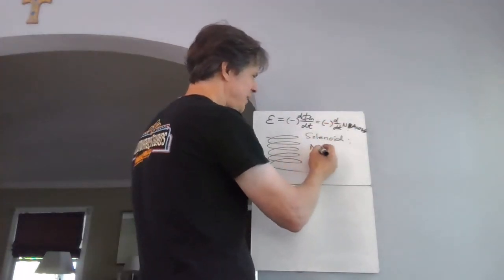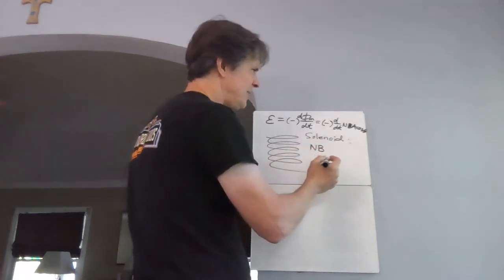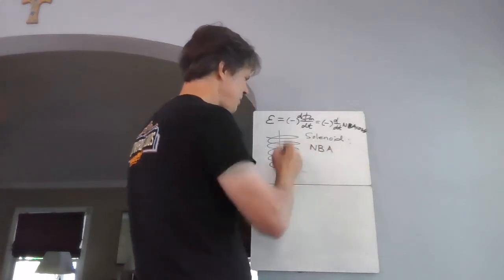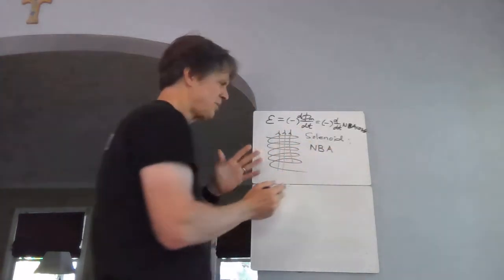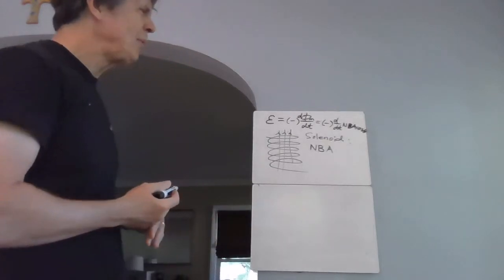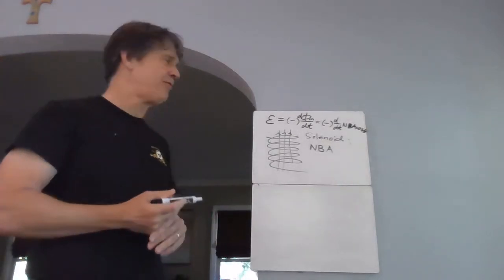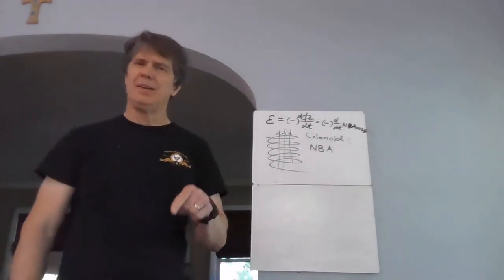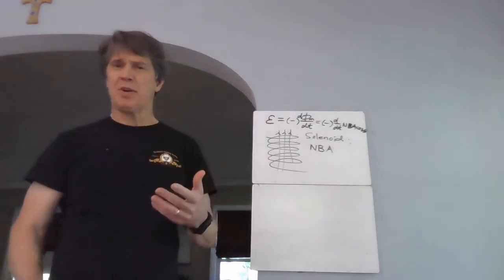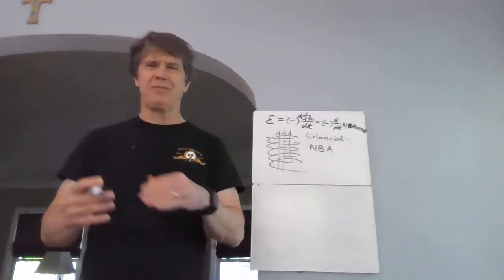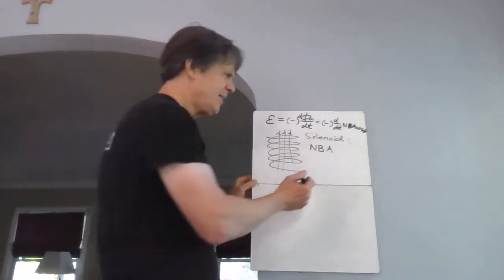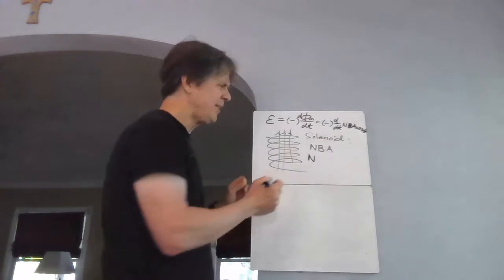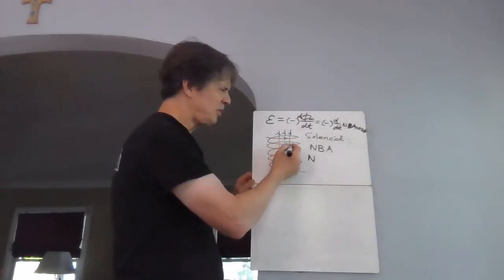So it's got an N, there's a B through it. There's the cross-sectional area of the thing. The cosine theta is easy because it's just one. So maybe there's a field through there. But why would there be a field through there? Well, there might be a field through there because there's a current running through it. Oh, that's weird. It would have a field through it because of the current running through it. Now, what's weird is it's going to fight back on itself. You'll see how that happens. So this field that's through it is going to be because of its very own current.